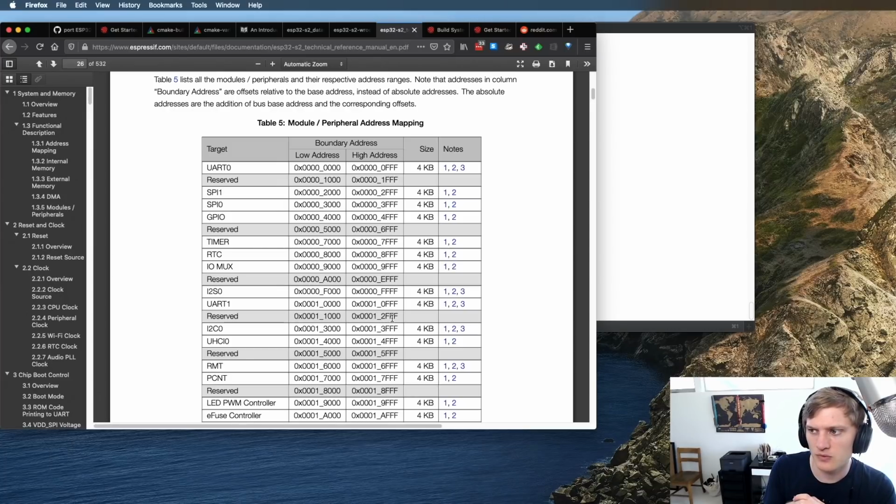And I think the reason that we're starting to see a shift is that the IMX RT is really interesting. The bottom of the line is the IMX RT 1010, and it runs at 500 megahertz. And so if we're going to sell that, the selling point of that is that it's fast. So I started looking into this, not to eke out every last performance bit, but I knew that the other detail you need to know about IMX RT is that it doesn't have onboard flash. So all of the code and the static data lives on the external flash. So it's something we have to address if we're going to be able to say we're using this chip in any sort of reasonable way. I spent a week on it doing initial investigations.